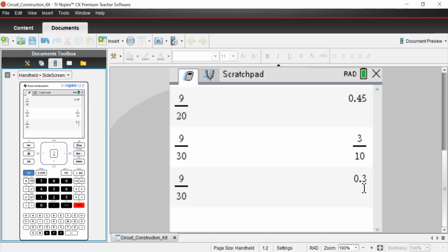So when we had one light bulb that was 10 ohms, we had 0.9 amps of current. Now that we have 3 10-ohm light bulbs, we have a third of that. We have 0.3 amps. Okay, and so current is what flows through the circuit. It's moving. Resistors resist the flow of electricity, and so this kind of makes sense, even from a conceptual point of view, that my current value is decreasing.